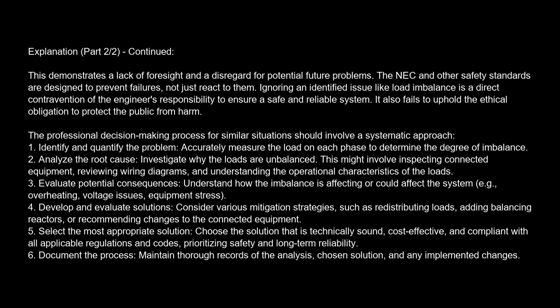The professional decision-making process for similar situations should involve a systematic approach. 1. Identify and quantify the problem. Accurately measure the load on each phase to determine the degree of imbalance. 2. Analyze the root cause. Investigate why the loads are unbalanced. This might involve inspecting connected equipment, reviewing wiring diagrams, and understanding the operational characteristics of the loads.